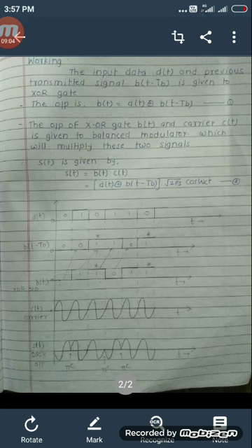Okay, because at the end of the first bit of b(t), it changes from logic 0 to logic 1, the phase of the carrier changes by 180 degrees. So for the duration of the complete second bit, it will be the phase-changed carrier signal. At the end of the second bit, the third bit is also 1, meaning there is no change from low to high or high to low, so the waveform of s(t) will continue up to the end of the third bit.